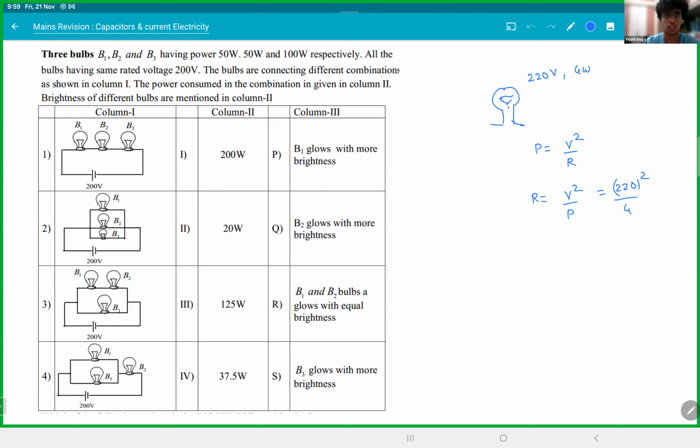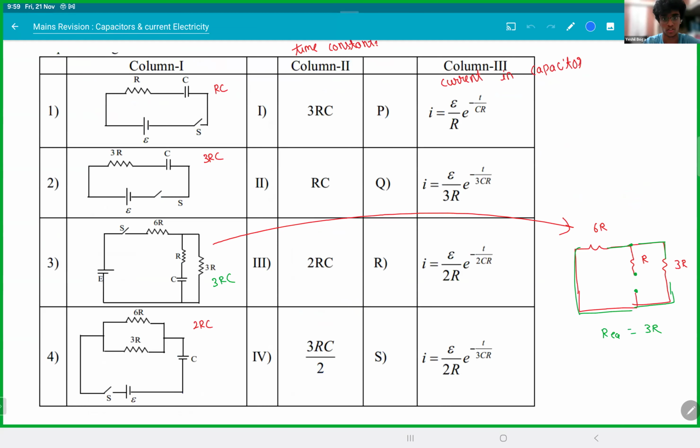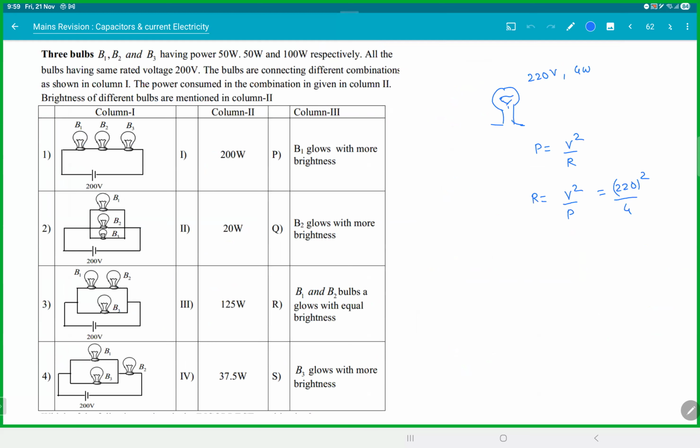So you're treating here there's a battery, right? Yes, if there is no battery, then there'll be no current only, right? What is the principle of superposition? If you have two batteries, V1, V2, put only V1, see what is the current. Put only V2, see what is the current, and then add them, right? But that's what I'm saying. See, when you consider the V2 battery, then you'll assume V1 is zero. You take one battery at a time. You can't take both.